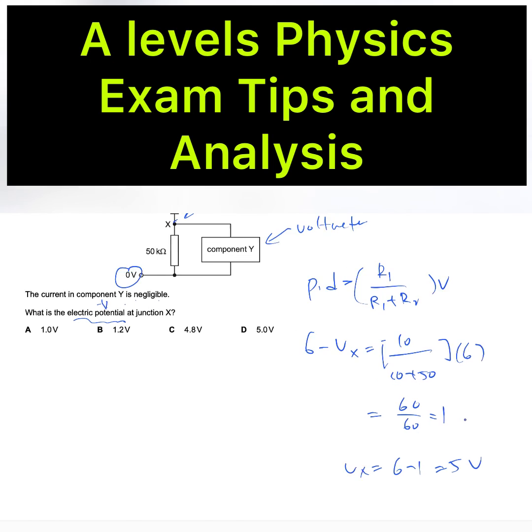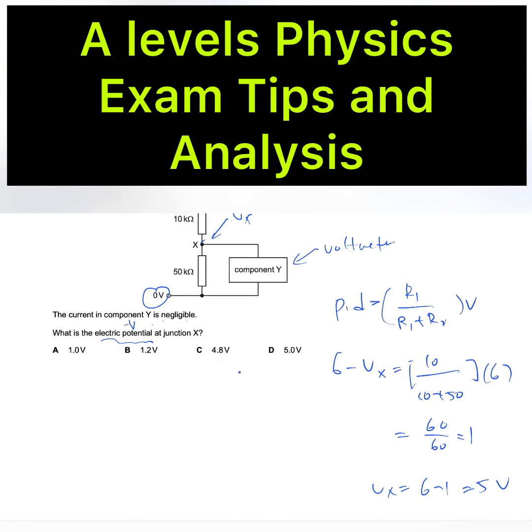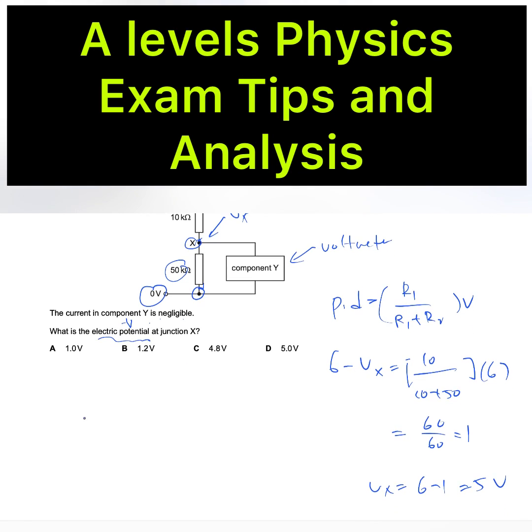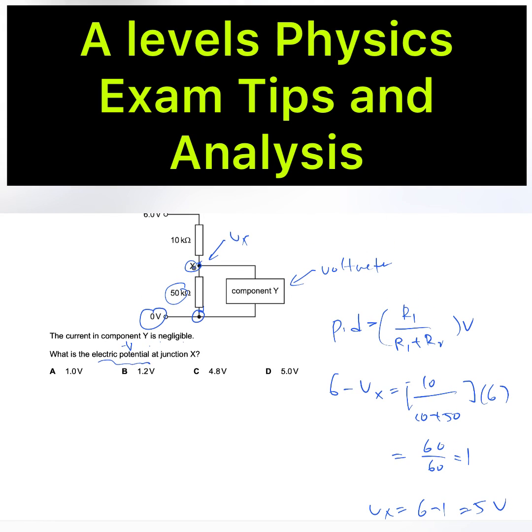What if you don't want to use this way? You can use another way. You have to consider the potential difference between this point and this point. We know that Vs has a higher potential because the energy comes from the upper side to the lower side; the current is flowing this way. So when you take Vs minus V0, you can just write Vs minus 0 as the potential difference.